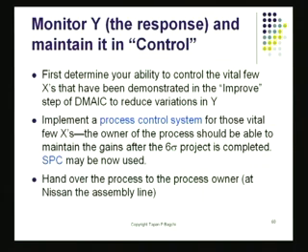You got to monitor the output. So basically what you really should do at this point is you got to keep track of this output as it comes off. So occasionally what you should do is you should take a car on the side and you should try to take that sticker off, that logo off. You should probably get down to the level of doing destructive testing, which is like you really peel the logo off and measure the force that is required to take it off. This way you'd be assured that my process is running at the setting where I set my process control system.